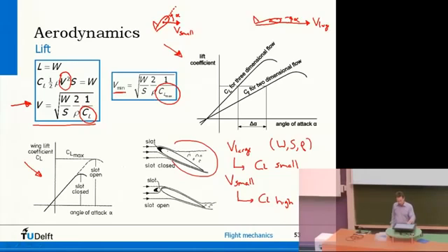And there are different devices. You can imagine devices at the front, at the leading edge of the profile, that may help the aerodynamics to stay attached to the airfoil. And if you do that, then CL max for the original case would be approximately this, and CL max for the case where you've opened this slot maybe a bit higher. So that helps you a lot.